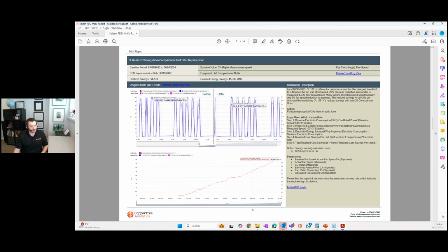A couple other questions here. Will all dampers close together with an AHU running, or will it do small groups of dampers? That was from Animesh. So if you're reviewing this, and I'll email you as well since you've already left, that depends. That's part of the test plan. We come up with the test plan in conjunction with the client and looking at the drawings and what data we have available for the system.